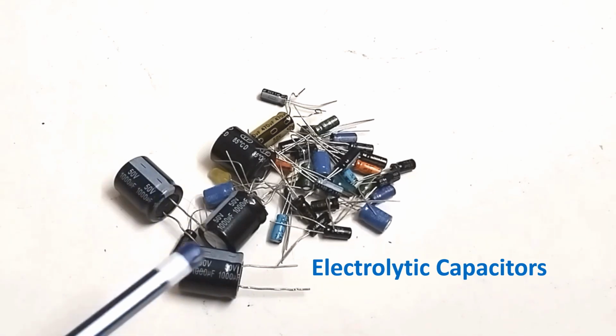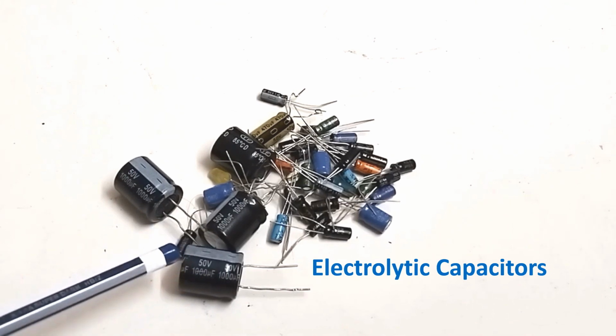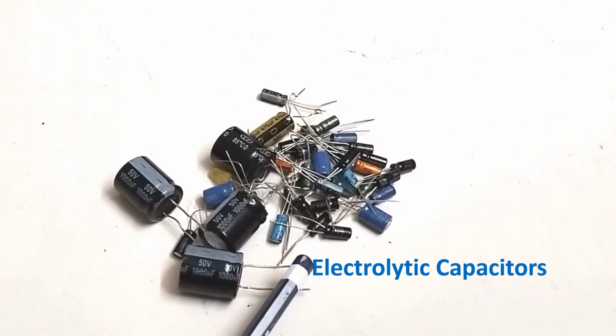You can see that this has a higher capacity rated at 1000 microfarad. The working voltage is given as 50 volts. And you can see that there is a minus sign here. That means this particular lead is for negative electrode and this one is positive. Another way of finding out is by the usual notation. The positive one will be longer. This is followed for most of the electronic components like diodes.